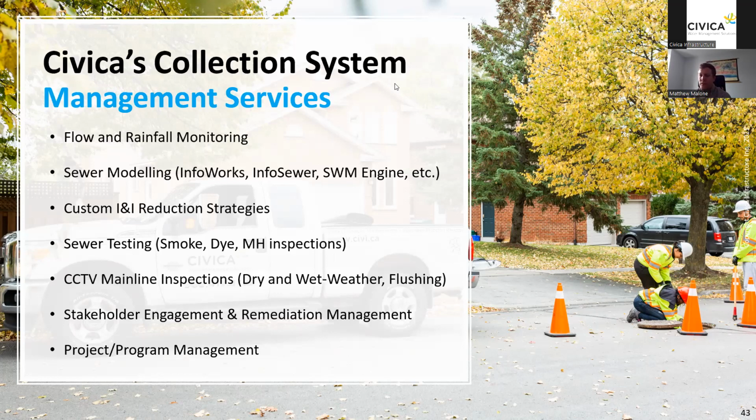Especially for those like trunk sewers and things like that, we try to put AVs in. We try and minimize any sort of backup or potential backup we can have in the system. Not that the flumes back up that much, but we're just trying not to put more into the flow than is necessary.